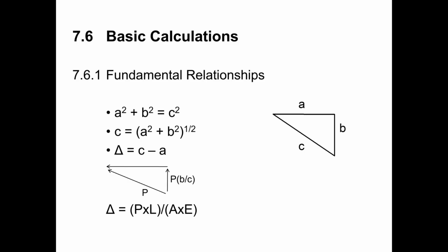that if they tension the strand in the draped position for 3 or 4 beams, due to the friction that builds up at each of those hold up and hold down locations, they would have a very difficult time getting the strands tensioned in tolerance, which means that they would then have to go to the end of the bed, the dead end of the bed, retension all of their draped strands in order to get them into tolerance.